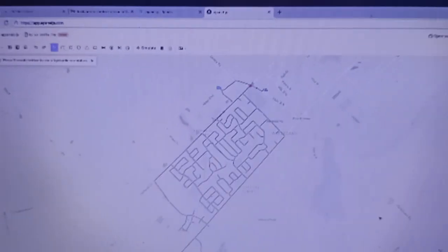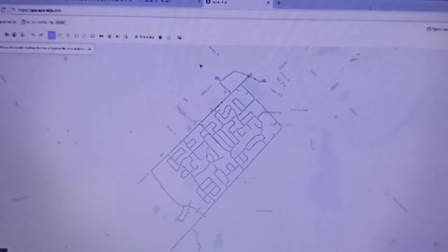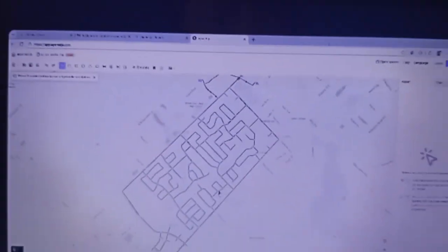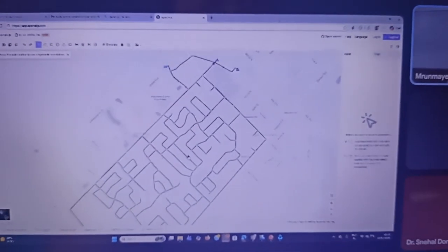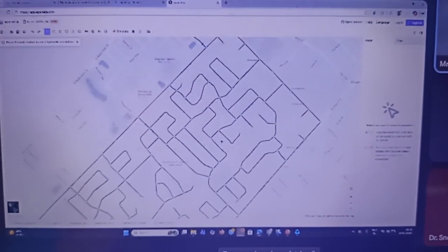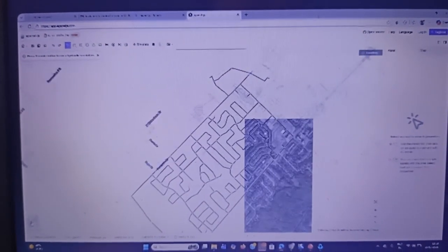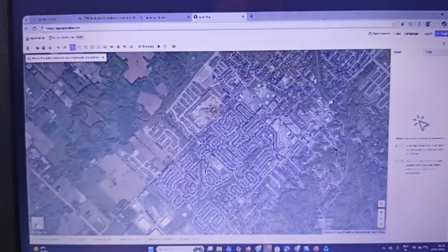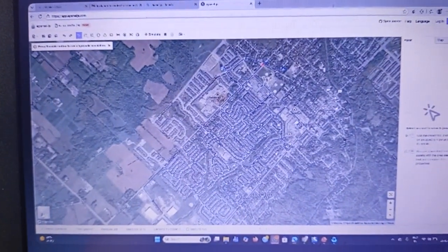If I show you this EPANET JS, for which we also have a license, you can see all the road network easily. Here also you can draw all your networks, everything is available, and you can run and simulate, which is a little bit online. But if you want to buy it, you can buy it also. This is an online kind of tool for EPANET. If you search for EPANET, you will know that it is highly advanced software, utilized throughout the world.